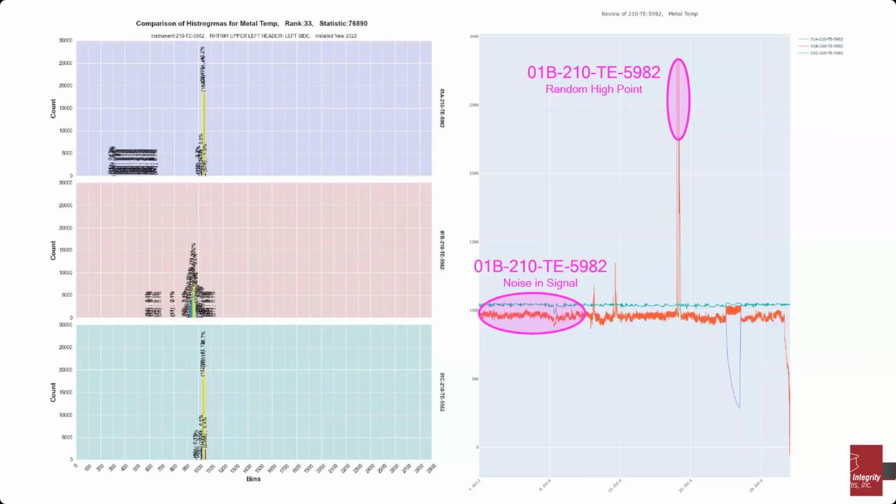Yeah, from our perspective, at least for the inspections that we know Duke has done on their attemperators, it's always been a challenge: if you do an inspection once and you find damage, then whoever did the inspection is going to recommend a very short interval. Whereas if you've got those TCs to monitor, you can see whether significant events are still happening after the fact, whether you've tested nozzles, replaced valves, etc. So it allows you to make those proactive decisions on maintenance-related activities.